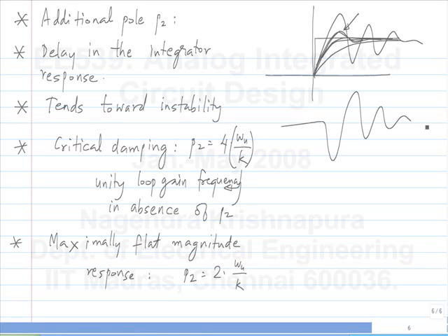What I mean is, if you have a voltage regulator, maybe at some point of time you have a certain amount of circuitry switched on, and at some other point of time you have some more circuits switched on. When you switch circuits on and off, the output voltage of the regulator is not supposed to change at all. In reality, you know that won't happen. In fact, I have shown you that in this particular case, I have applied a step at some point. But if you apply a step at any point of this loop, you will see the same denominator and a similar kind of response.